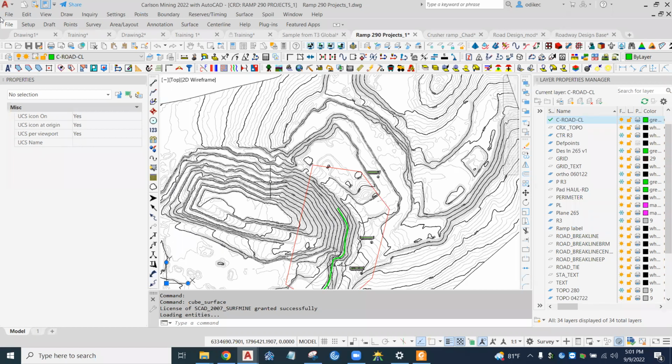until it hits the ground where you're trying to go. And so now you know where to put the ditch. You just follow the line, and then you drop that line on the surface. Well, it's already created to be on the surface. You just drop it down however deep you want the ditch to be. Offset it if you want it to be a certain width at the bottom.